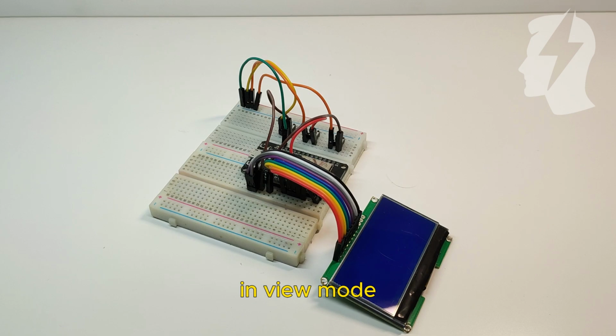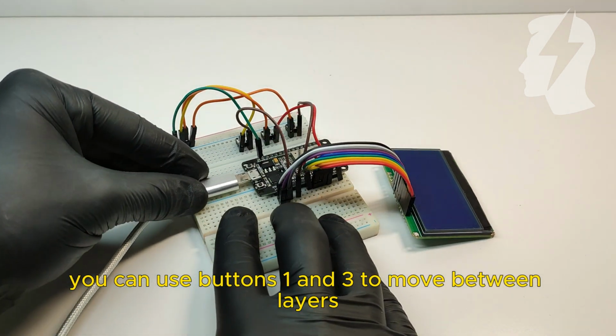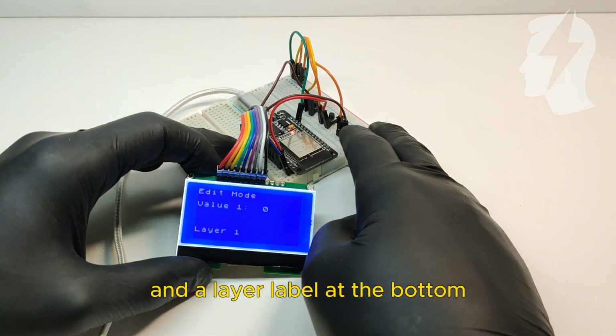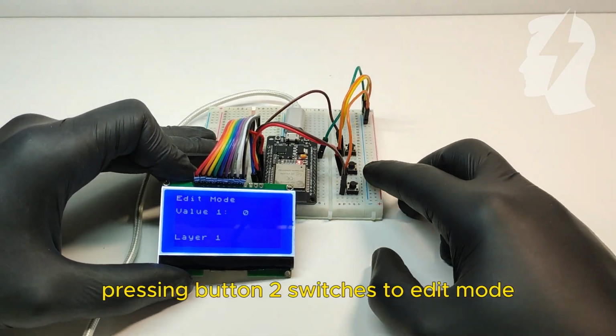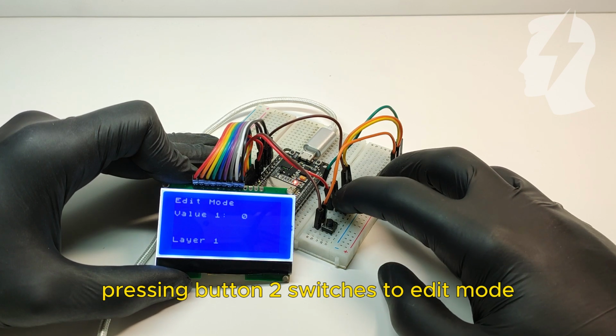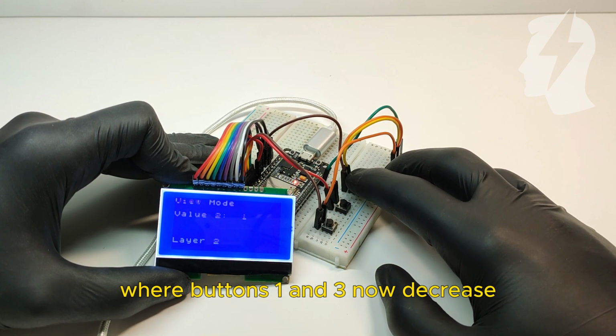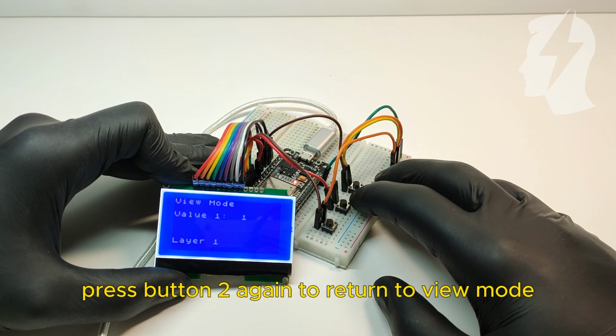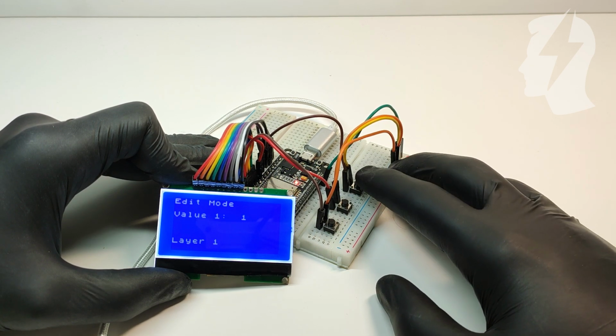In View mode, you can use buttons 1 and 3 to move between layers. The currently active layer is shown with its value and a layer label at the bottom. Pressing button 2 switches to Edit mode, where buttons 1 and 3 now decrease or increase the value of the selected layer. Press button 2 again to return to View mode.